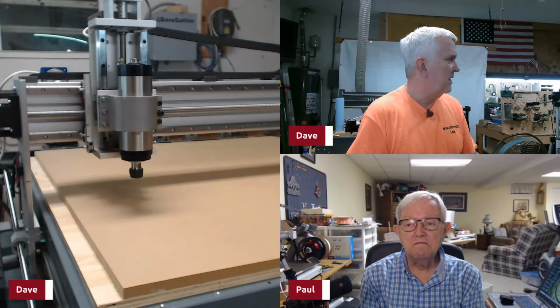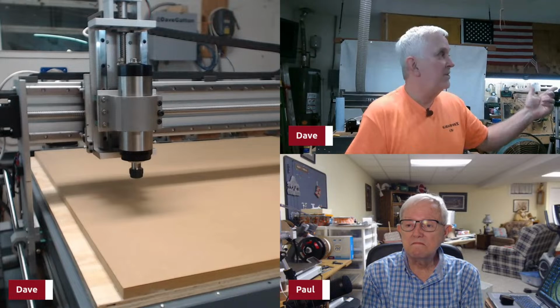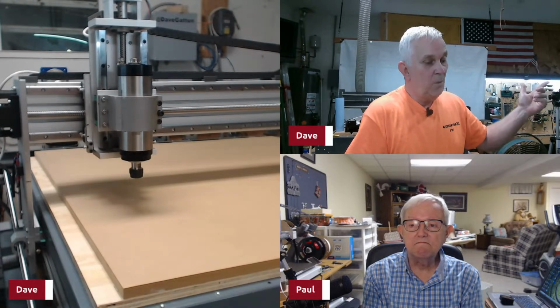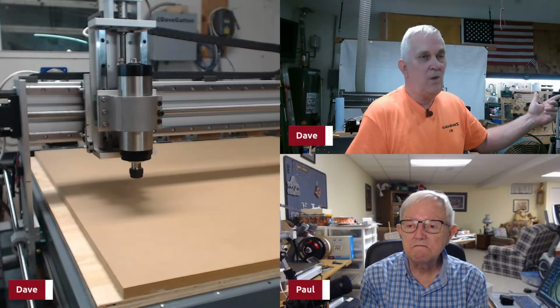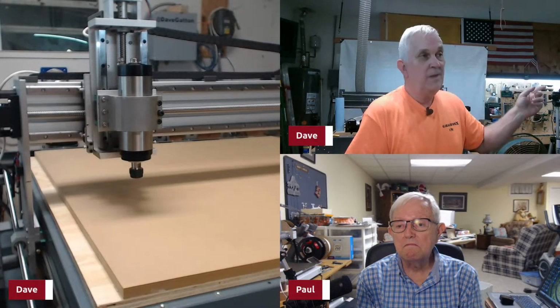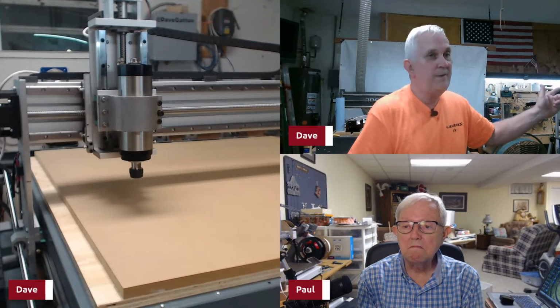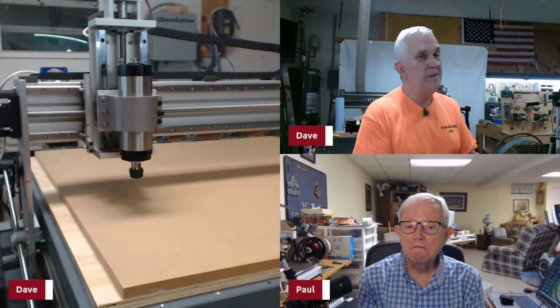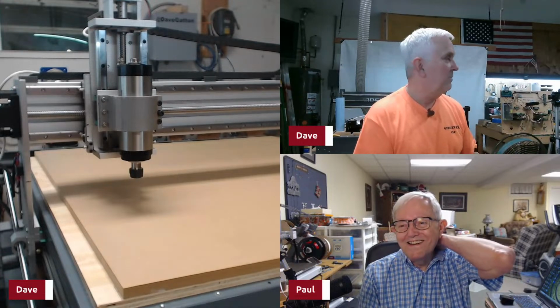And then there's a lot of miscellaneous stuff. The linear rails and bearing blocks, like I said, I bought them off Amazon. They're the HGR 20s, which I didn't know this, but I was trying to get information on the Altmill to see what pitch their ball screws are. I couldn't find anywhere where it said that, but it did say that they use the HGR 15 linear rails. So their linear rails are not as beefy as my linear rails. Just saying.